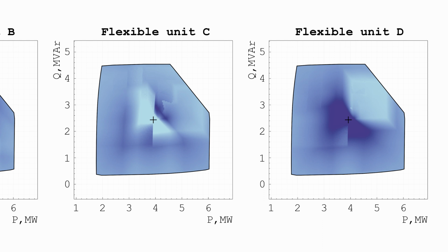So as I said, unit D, the cheapest unit, is producing a lot of flexible power in the beginning for low magnitude flexibility requests, but then suddenly its share of flexible power drops. And especially we can see that it drops a lot once we start moving towards the direction of active and reactive power consumption increase.